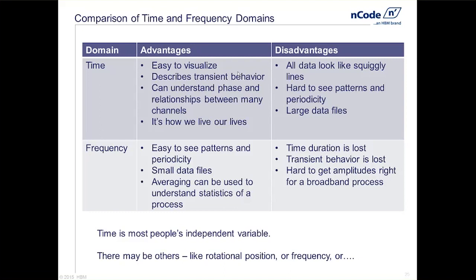So just a couple of things to keep in mind here, advantages, disadvantages of looking at things in the time domain or in the frequency domain. There are also other ways in which we can look at things that, depending on the type of structure you may have, a common one that comes to mind would be looking at things in the rotational or the position domain. Engine analysis is done quite a bit in this sense, where we look at orders, we look at things that are occurring once or multiple times per revolution of a crankshaft or a camshaft.